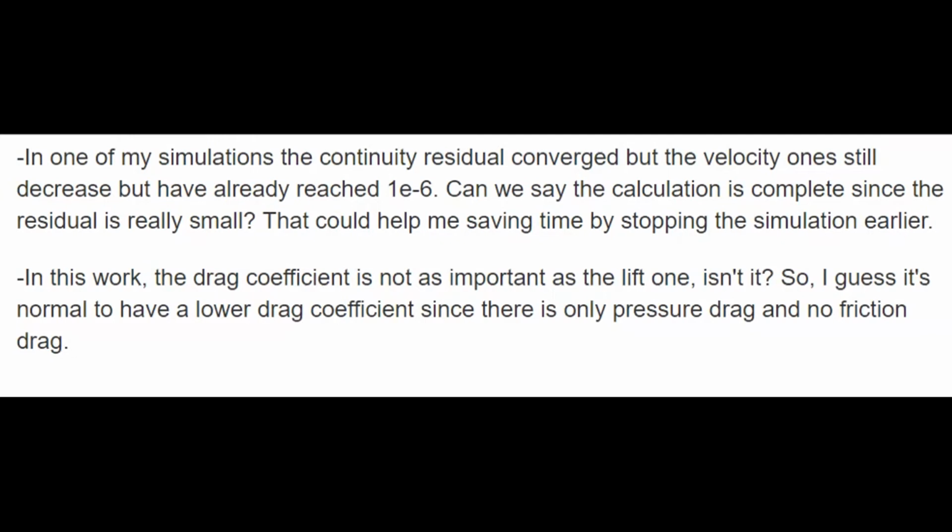For slowly converged processes, for example, when you are simulating heat transfer together with the flow, which have very different characteristic times, or flow and chemical reactions that have very, very different time scales. Then one process looks like it already converged, but the other process is still not converged. In this case, for one process, we put a bigger value of residuals, for another, we put a smaller value of residuals.